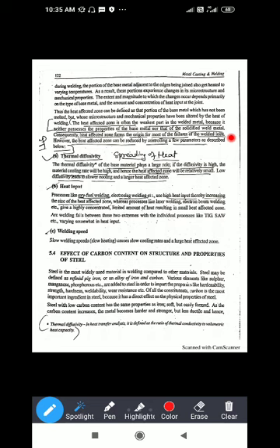Okay, because of that heat, the affected part becomes weak, and that is going to break when you apply the load on the welding part. So for that reason, you have to reduce the heat affected area.